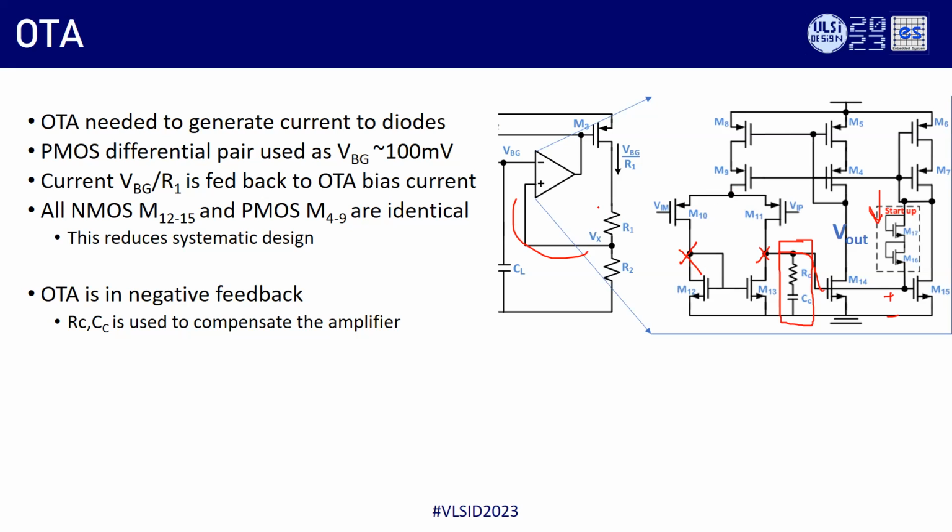So basically the systematic offset will be reduced through this shallow bias. Imagine there is no shallow bias like this. Some people fear that a startup is required and that it might not start, so they don't use this kind of traditional approach. They simply put a diode and a resistor, so that it relies on the supply. As long as there is a supply, there is enough current, which varies across PVT and so on, and it doesn't track offset, but it's robust, so people do that.